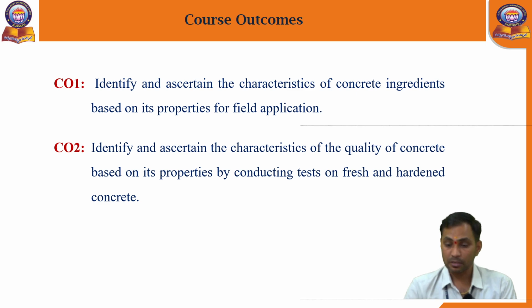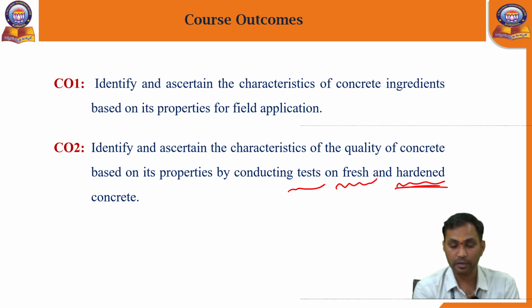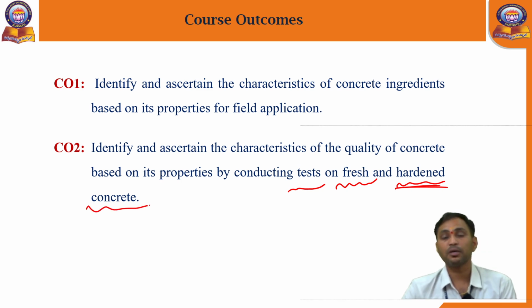You can observe here, fresh and hardened concrete. For fresh concrete, he has to find out its characteristics by conducting a test, that is the workability test. After 24 hours, the student has to check the quality of hardened concrete, that is testing of hardened concrete, the strength test.